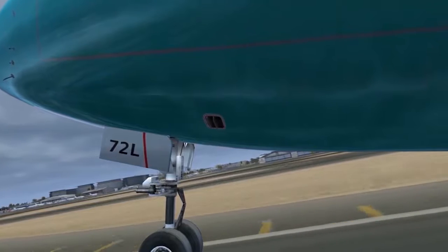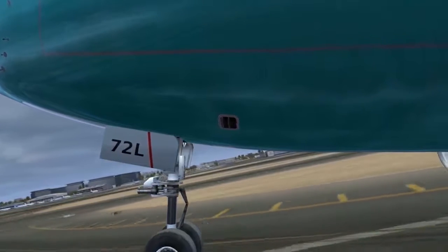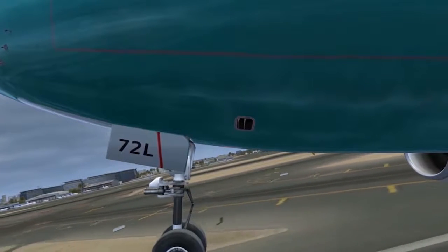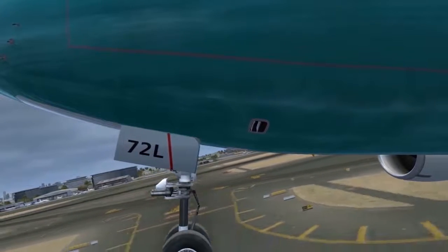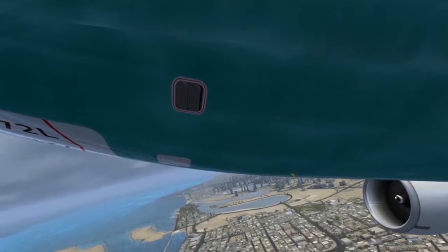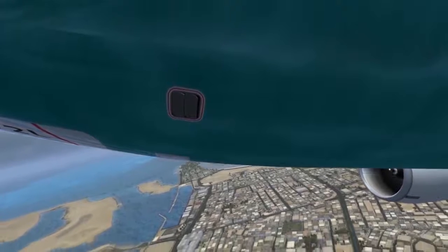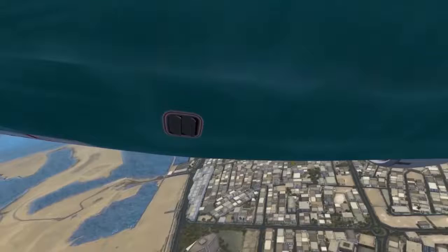They move the outflow valves to a slightly less open, more closed position. This pre-pressurizes the cabin to 0.1 psi above takeoff field pressure to avoid any uncomfortable pressure bumps for the passengers during rotation. Whenever the air-ground sensing system switches from ground to air, or when the aircraft climbs beyond 1,000 feet, the ASCPCs enter climb mode.